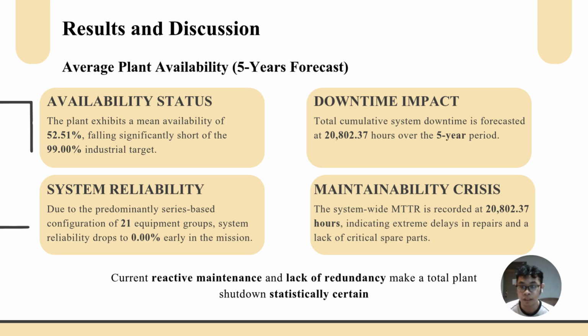And the primary driver behind this low figure is an astronomical system-wide MTTR of 20,802.37 hours. So this indicates that under the current condition, the plant is crippled by extreme logistics delays and also the lack of spare parts, where a single failure can also lead to years of cumulative downtime.